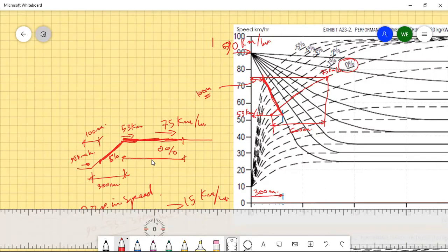So it will continue for 600 meters after ending the sharp grade. This is to allow the truck to accelerate to reach 75 kilometers per hour. We are not looking for the truck to accelerate to 90, no, but this is the acceptable level, that the drop is 15 kilometers per hour.